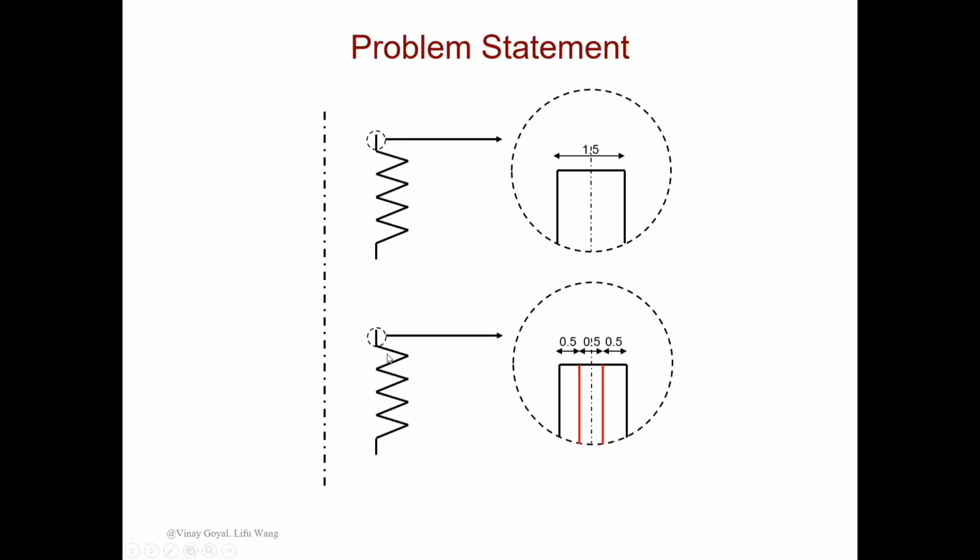And for the bottom model, we make three shell elements. All of them have 0.5 in thickness, but in the joint of the three elements, we actually use a cohesive contact for them. So we're going to compare these two cases and also compare to our previous result.